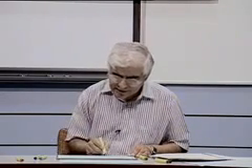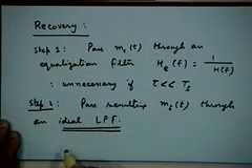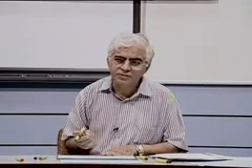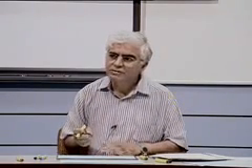Of course, this requirement of an ideal low pass filter can be a little stringent, because you can't physically realize ideal low pass filters. So how do you handle this situation? The fact is that your low pass filters will not be really ideal. So in practice, your sampling rate should be somewhat larger than 2W. I have not gone into the details of the sampling theorem here. I am assuming that all of you know the reason why you require an ideal low pass filter.